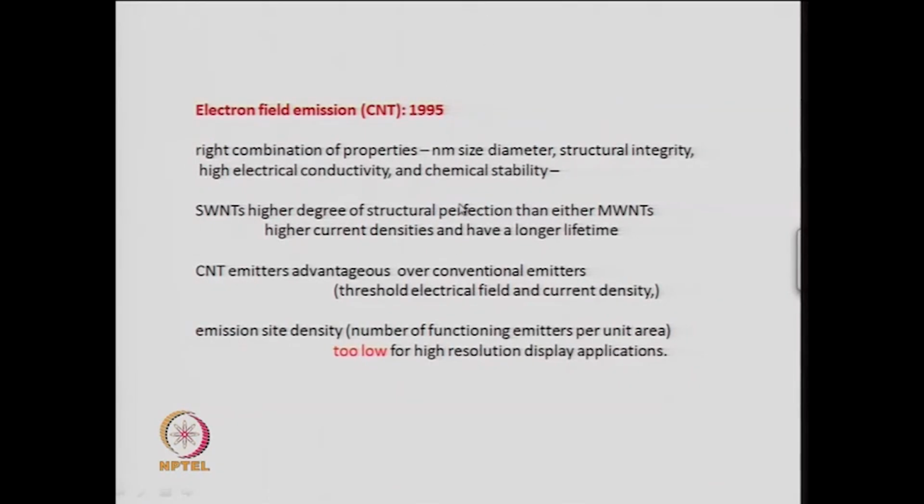These are very thin. So, you have these nanometer size diameter tubes, and you need these thin tubes with fine tips for good field emission. And the other thing is their structural integrity, but most important is their high electrical conductivity. So, their narrowness and their high electrical conductivity are two very important factors for any good field emitter. Apart from that, of course, you must have structural integrity and chemical stability for use over a long period of